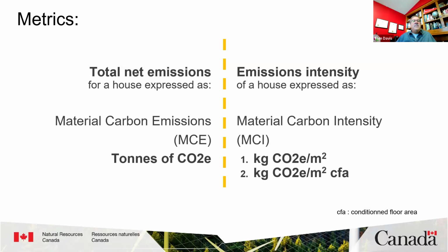If we only look at MCI by total floor area, the lower embodied carbon that is typical of less finished areas like garages and basements actually makes the carbon use intensity look better. To prevent incentivizing adding more low carbon spaces to have a positive impact on MCI, we choose to focus on the material carbon impact per square meter of conditioned floor area.